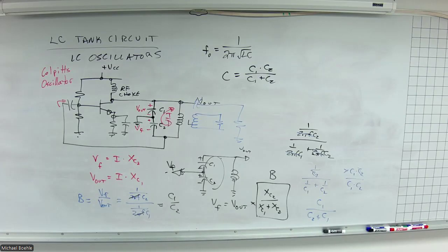The advantage of this connection, just a matter of which amplifier you want to use. Common emitter or common base. We need voltage gain either way, right? So what's one thing we cannot use? Cannot use a common collector amplifier because it does not have voltage gain. And then he also shows a circuit using a JFET instead of a transistor.